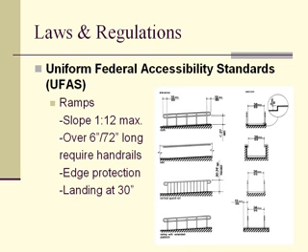Another specific requirement for ramps is that once they rise over 30 inches, they are required to have a landing, and that landing, if it is in just one direction, can be as wide as the ramp leading to it. Now, when you change directions, that landing has to have the 60-inch turnaround space that we have spoken about in the past, so somebody in a wheelchair can wheel up to that landing, make the turnaround, and wheel in the opposite direction, basically to take the switchback or the other portion of the ramp. So the concepts of the building blocks of that turning space start repeating themselves throughout these elements.